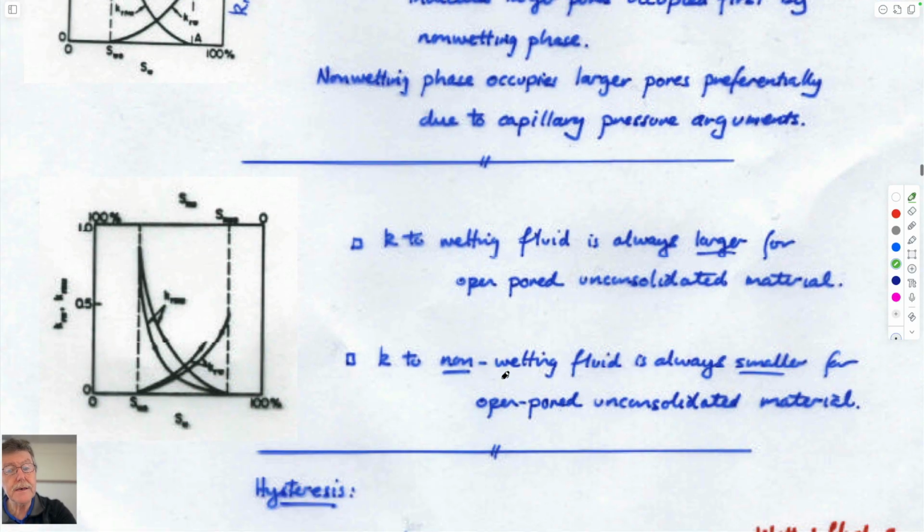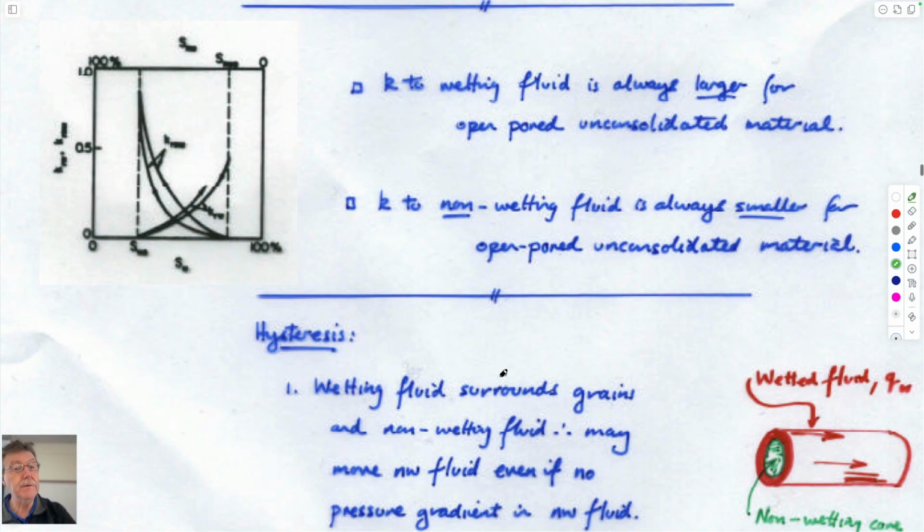So you see this. There are other quirks of behavior. If you look at the relative permeability as you put more vapor into the sample, it goes up one particular trajectory. But once it gets there, if it returns and you start saturating it with water again, so in other words, if you put more vapor into the system initially to go up this curve, and then once you get to a location, you push water back into the system to go in the opposite direction, you don't pass along the same curve. There's hysteresis on it.